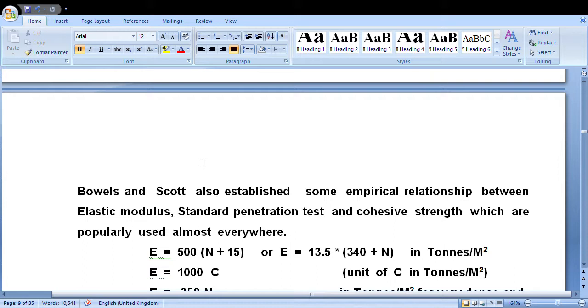In case of clay soil, elastic settlement and consolidation settlement, that is primary settlement and secondary settlement, are the governing factors. Whereas the immediate settlement in case of clay is not simply noticed. However, in granular soil, where pore water can easily ooze out under nominal loading, that type of settlement is there. That's the immediate settlement.